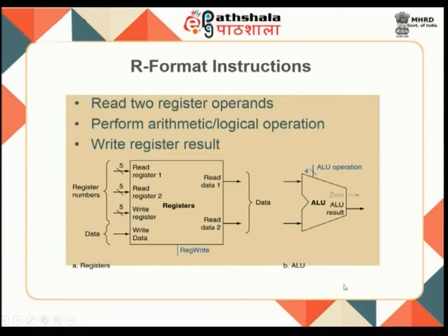And what will happen for an ALU operation is, the ALU will take in 2 inputs, one from your register specifier here, the other one again from a register specifier or an immediate operand that is sign extended. So, the ALU will perform an operation. What operation it will perform will be decided on the ALU operation that is given here,